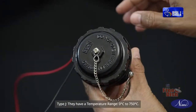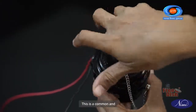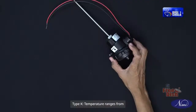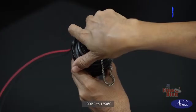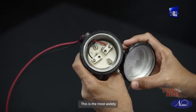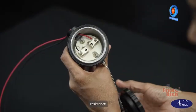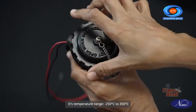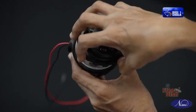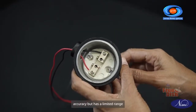Type J. They have a temperature range from 0 degrees Celsius to 750 degrees Celsius. This is a common and cost-effective option but not ideal for high temperatures. Type K temperature ranges from -200 degrees Celsius to 1250 degrees Celsius. This is the most widely used thermocouple due to its wide temperature range and good corrosion resistance. Type T. Its temperature ranges from -250 degrees Celsius to 350 degrees Celsius. This is suited for lower temperature applications and offers good accuracy but has a limited range.